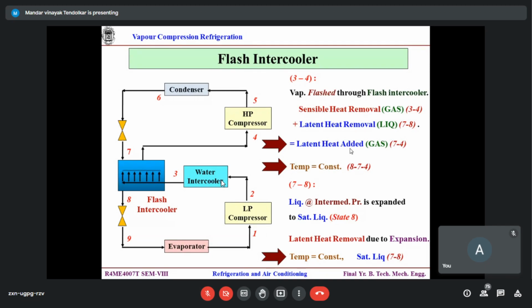Liquid flashing is more like, imagine a tub filled with water and at its bottom a garden watering pipe, and you perforate it and pass air. तो जैसे जैसे air bubbles ऊपर आएंगे, that is somewhat similar to a flash intercooler. So air resembles our steam, or steam नहीं क्या बोलेंगे, high pressure, high temperature gas, refrigerant vapor.